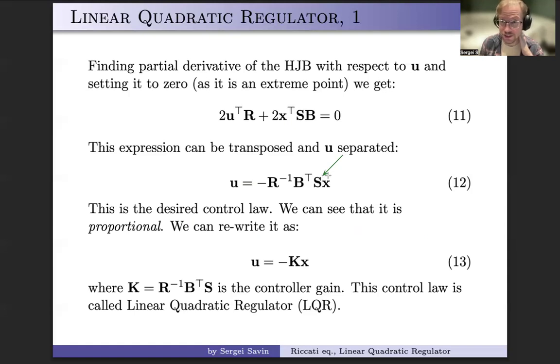But other than that, you could already apply it. So it's pretty good. And notice we also proved that the best possible control policy is actually linear. It is just this, minus Kx. So this is the control again. It's quite impressive, really quite impressive.